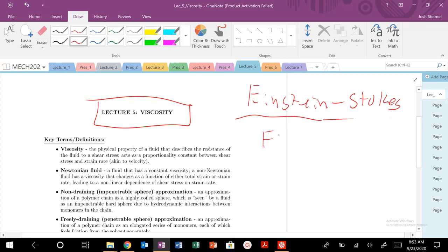If there's anything that you should remember from fluid mechanics, or at least as a polymer physicist, this is a really important and critical equation, which is basically your viscous drag, or your Stokes drag force. Hopefully this is covered in basic mechanics. The force of your viscous drag is going to be 6 pi times your viscosity times the radius of your sphere times the velocity at which it falls. But anyways, we'll get more into this later.